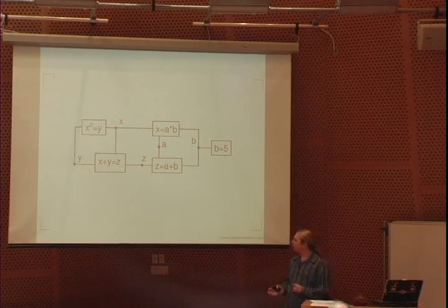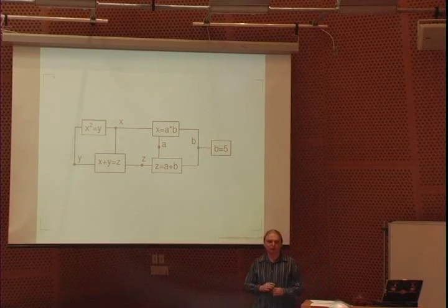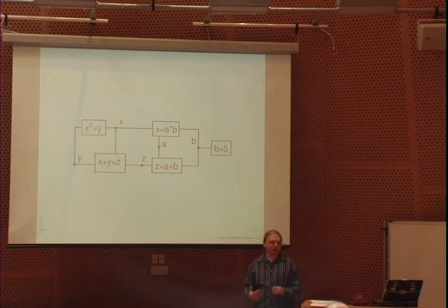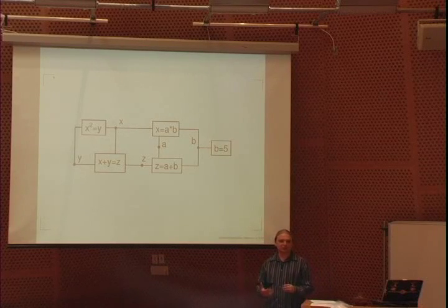There's a local stability criterion. What I mean by that is that if you follow a methodology for designing these individual blocks, you can plug them in not quite arbitrary, but almost arbitrary global configurations, and the local stability criterion guarantees global stability. This is nice because it lets you build complex systems. In traditional analog circuit design, you have the problem that if you're trying to build a complex system, you need to do global analysis of every loop to determine stability. In this case, you don't need to do that.